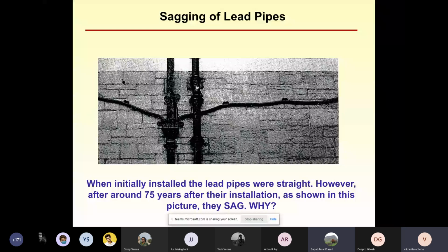The air resistance. Air pressure is there, that is one loading, but that is a small part of the loading. There is something else which is causing enormous stress. Heating of the blades. Thermal stresses to some extent, again not too much. There is something else. Rotating of the blades. What will that do? The centrifugal force. Centrifugal force will stretch the blade. So there will be a large tension generated within the blade as it is rotating at high speeds.